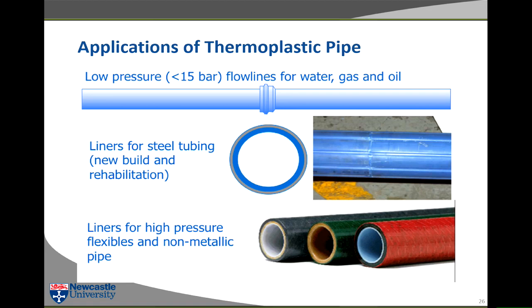If you have to take the pressure off for some reason, there is gas present between the liner and the wall of the pipe, and there may be uneven areas in the wall, there may be welds, there may be little spaces between the liner and the wall. As soon as you remove the pressure, this gas in the interface and in the annulus between the thermoplastic liner and the pipe wall can expand and collapse the liner. So there's a big problem with using these in oil and gas because of liner collapse, and this problem exists in all of these types of pipes. You have to be careful.